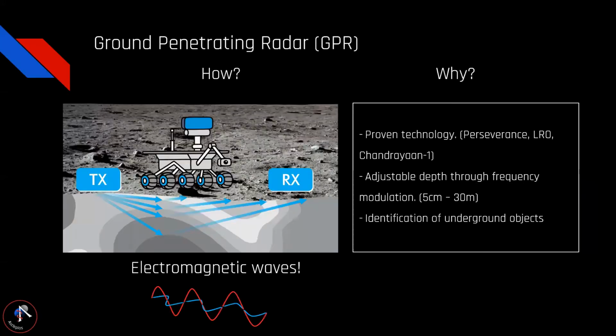How does the ground-penetrating radar work? It is a method that consists in the emission of electromagnetic waves through the ground in order to measure their travel time. This time might change depending on the underground layers that the wave encounters, letting one part of it be refracted deep underground and the other be reflected back to the surface.